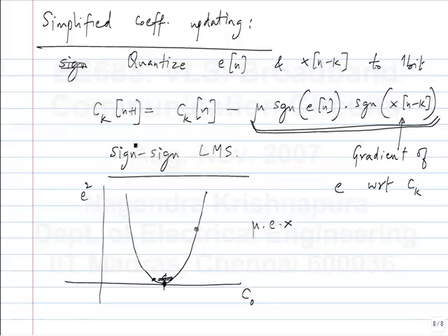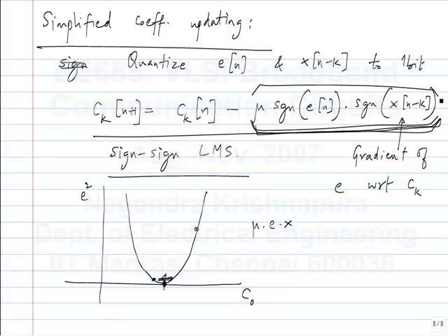So can you intuitively say what's happening here with sign LMS? Or you can think about it, I think we are out of time, we can discuss it in the next class. What is the meaning of this? It turns out that this can be stated in words very easily. By looking at the value of y, you want to get it to the right value. So you simply look at whether y is greater or lesser and then you change the coefficients in one way or the other.